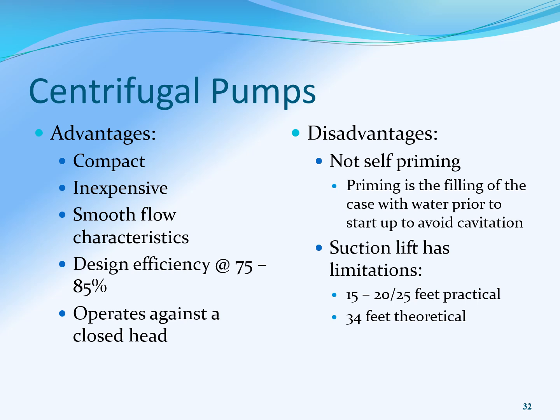But then they do have a suction lift of, approximately practical, as you can see here, 15 to 20, sometimes 25 feet. Theoretically it is 34 feet. If you've taken the distribution math course, you know that to get that number, it is 2.31 times 14.7, and that's how you get like 33 point something, rounded up to 34 feet theoretically.